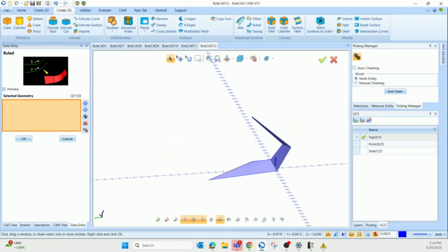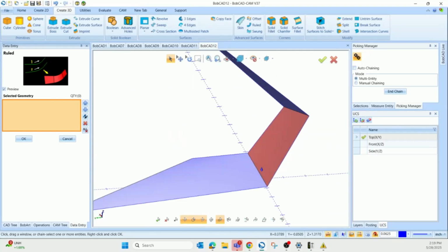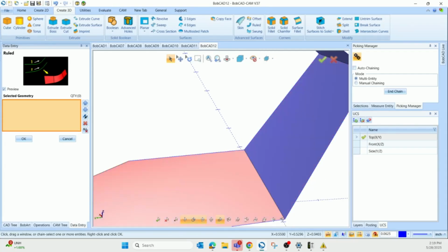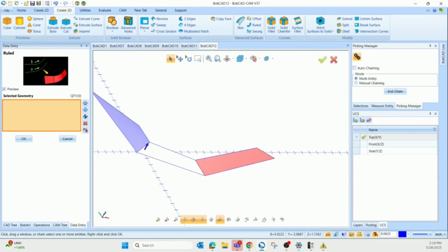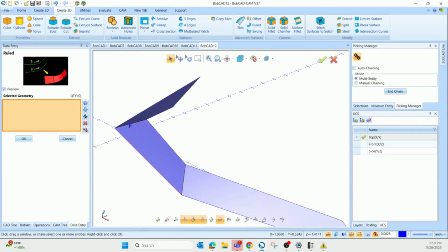Sort of a cross section, I guess, but it's not one surface, you can see. It's 3 different surfaces that terminate in between the intersections here. You can see this is the example with lines. You can see the example in ruled surface. Maybe if I did a spline, it will do it a little more continuously or a smoother surface there. But that's what the ruled surface is all about. It creates a surface using the selection of 2 wireframe chains with a linear blending between the entities of each chain.